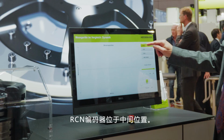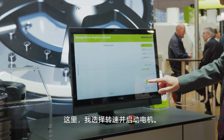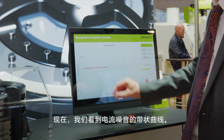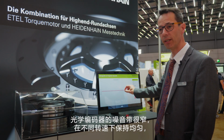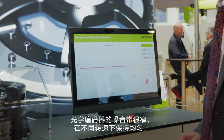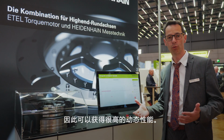This is the RCN encoder in the middle. I can select the speed and start the motor here. Now we see the current noise, which is this band here. This optical encoder's noise band is very narrow and uniform under varying speed. So high dynamic performance is attainable.